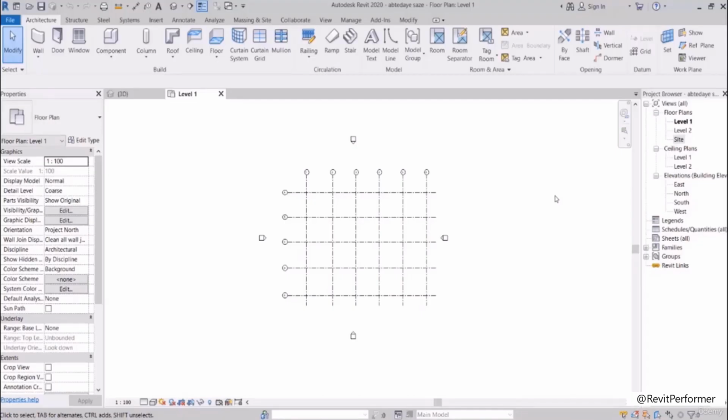In phase 2, at first the structure is prepared, and then the other groups will import it and start working on it. Therefore, the structural file defines the 0 spot. Usually where two center lines cross is known to be the 0 spot of the project.